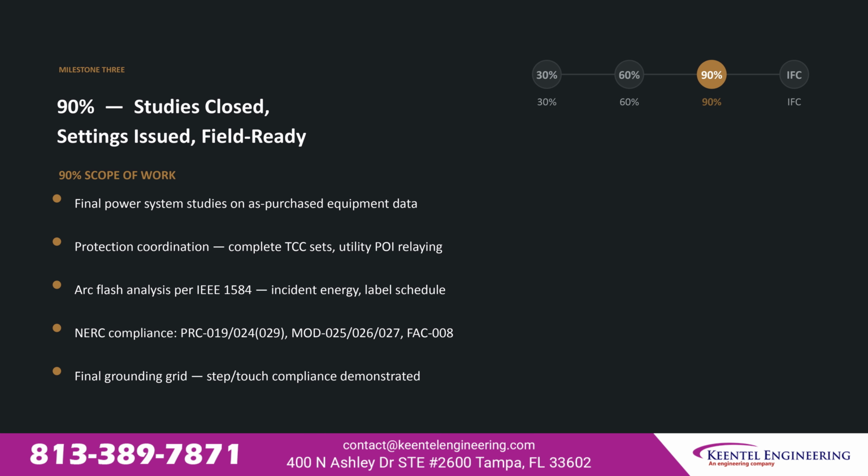At 90%, the analytical work closes. Final power system studies run on as-purchased equipment data: certified vendor test reports, not assumed values. Protection coordination produces complete time current curve sets and utility POI relaying. Arc flash analysis per IEEE 1584 produces incident energy values and the panel label schedule.